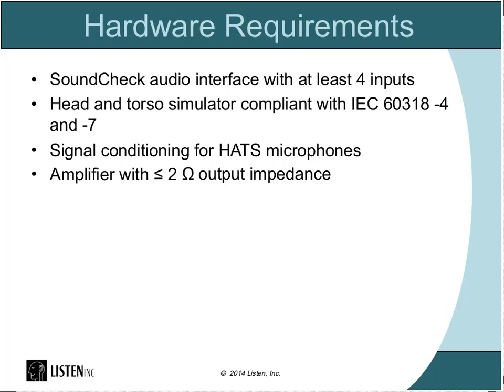You'll also need a head and torso simulator that's compliant with IEC standard 60318-4 and -7. Examples of that would be the B&K HATS or the GRAS KEMAR. There might be a few others out there as well. But in order for them to work with the EN standard, they have to be compliant with that IEC standard as well. You'll need some sort of signal conditioning for your HATS and microphones.